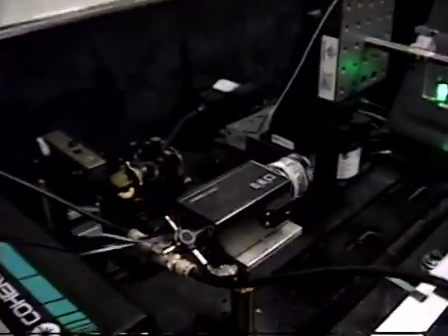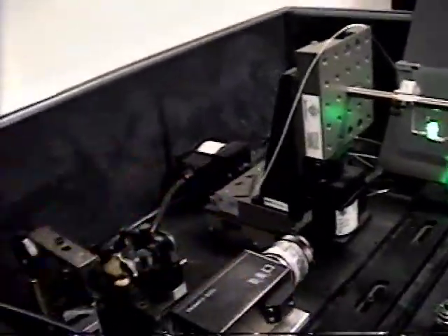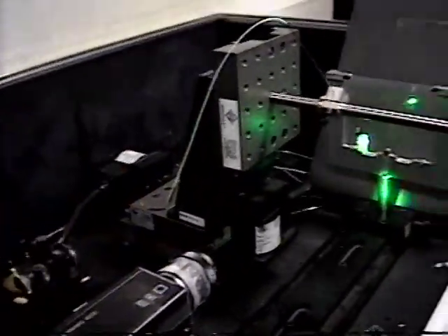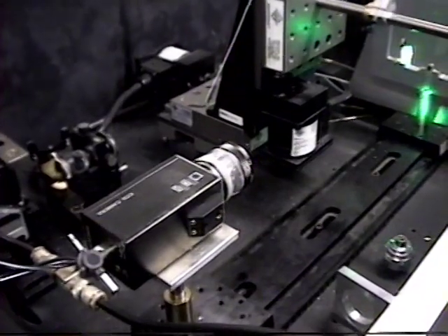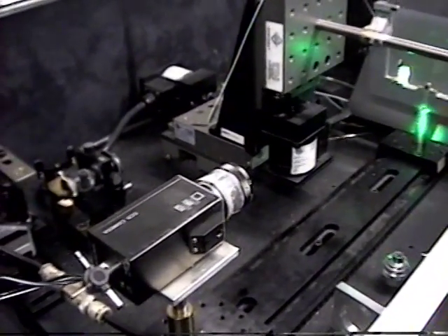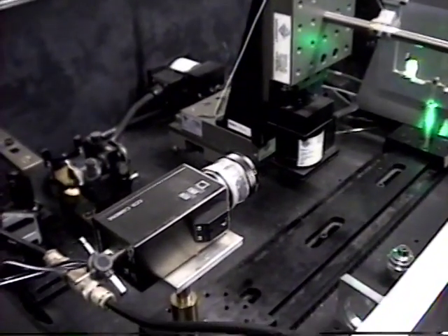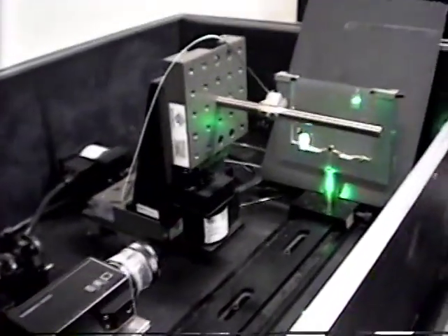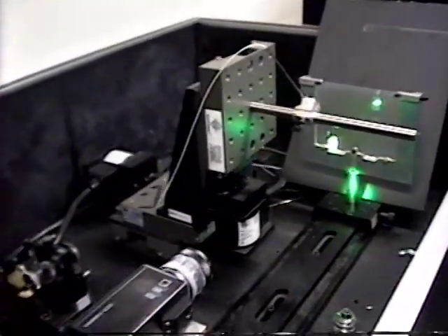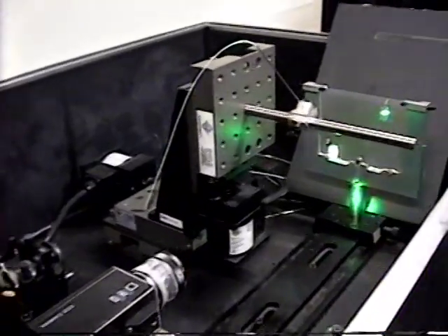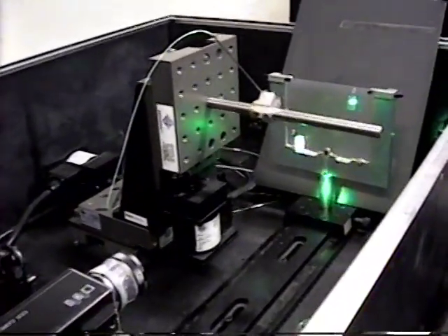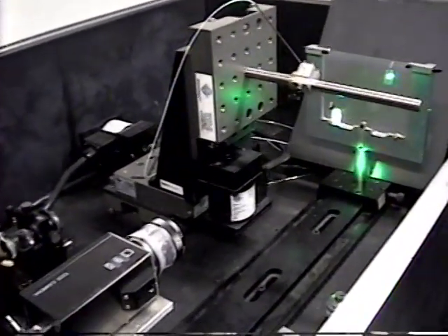I'll probably stop messing around with the lens for a while because we have a lens here that does a pretty good job. By the way, the depth of focus of this thing, with a smaller pinhole in place, is much better. It used to be up around 2 millimeters, and now it's under a millimeter total depth of focus, about plus 0.5 to minus 0.5 millimeters, roughly, on our images, which is very exciting to me because that's my threshold for what I think is a workable PIV system, to give a millimeter resolution, at least in the depth direction.